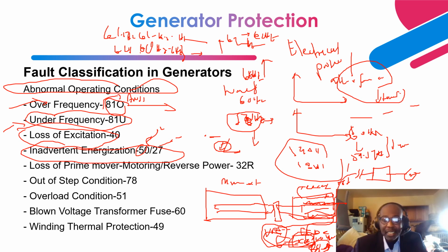You have 18 kV that is stepped up to, let's say, 115 kV. Then you have a breaker here. When you take this turbine generator set offline by tripping this breaker, the turbine generator shaft will be on a turning gear because it is hot.